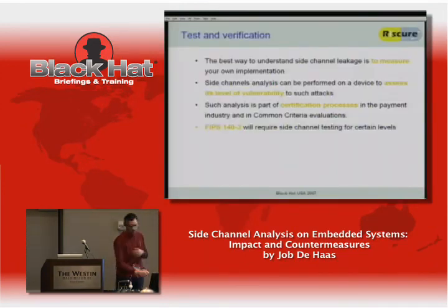I think I need to start finishing off, so I'll just show you the RSA at the end. What I wanted to say about this is that what you see using these attacks is that it's actually pretty difficult to determine if your system is leaking. You really need to measure and test to discover what kind of leakage your system has. And it's quite difficult to predict this. In this sense, it's a very fuzzy field. There's no theory of countermeasures where you use them and you're done. So verification is pretty important.